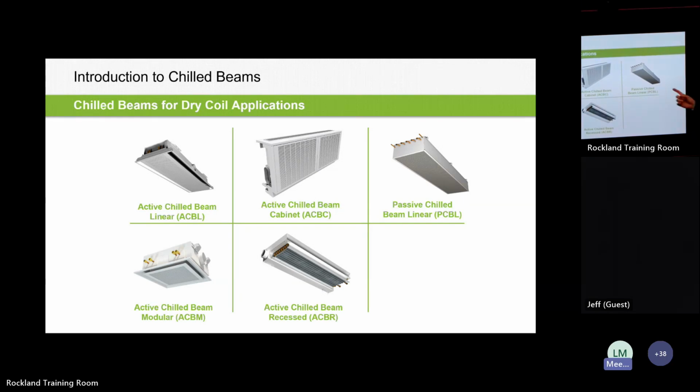classroom applications. The passive beam, which is kind of reversed because you always think of starting with this type of concept. The passive beam is kind of the earlier invention, or the one that came first, where you've got just buoyancy driven airflow. So passive being that you don't have a primary airflow connection to it. So it's just using natural buoyancy and that warm air getting up behind that coil and cooling off and falling down into the space. So it's a supplemental or auxiliary cooling component to the system.